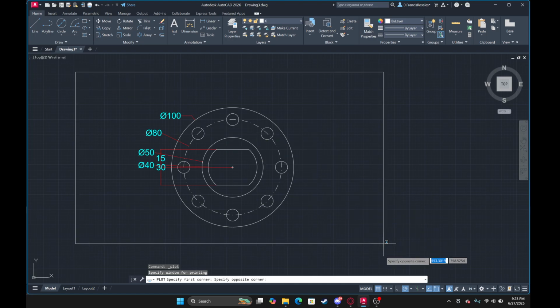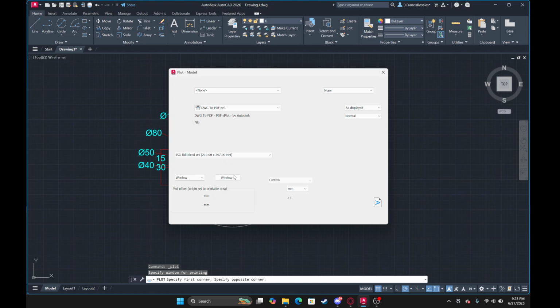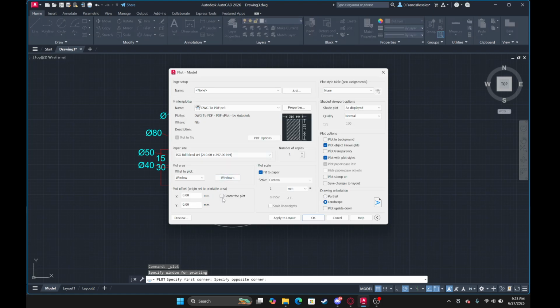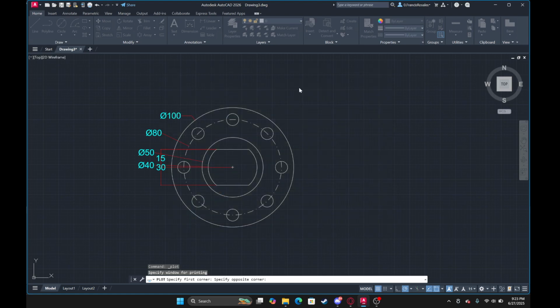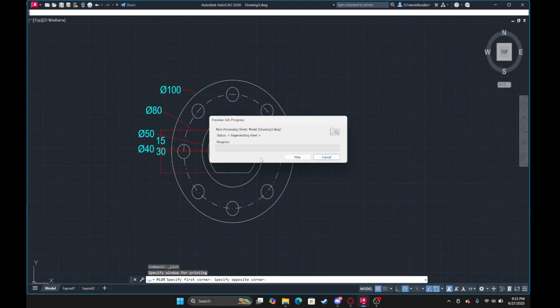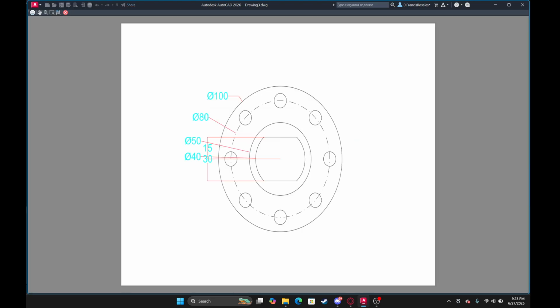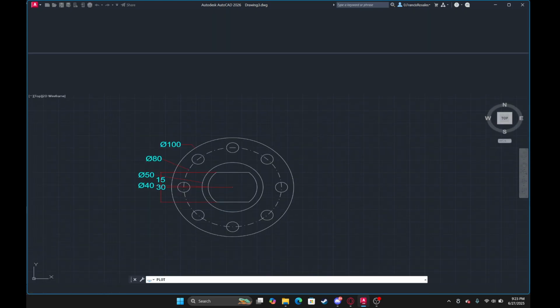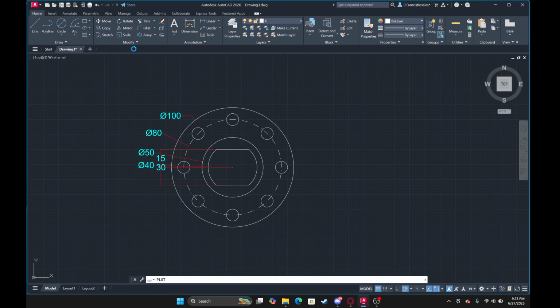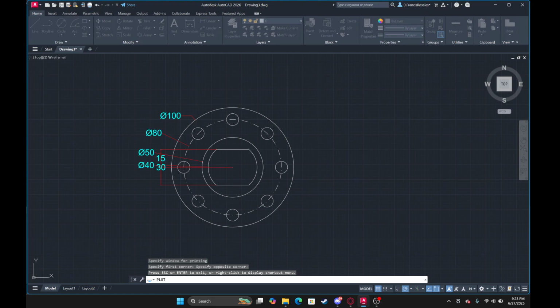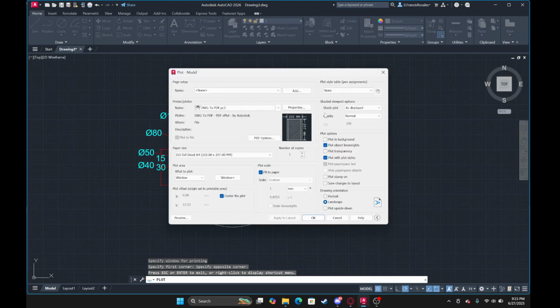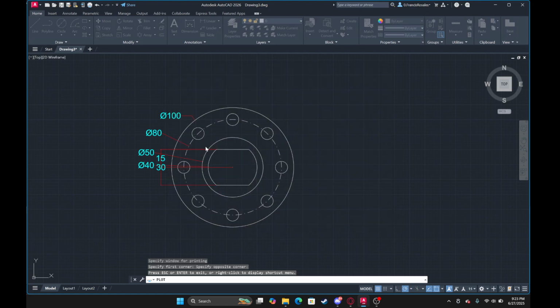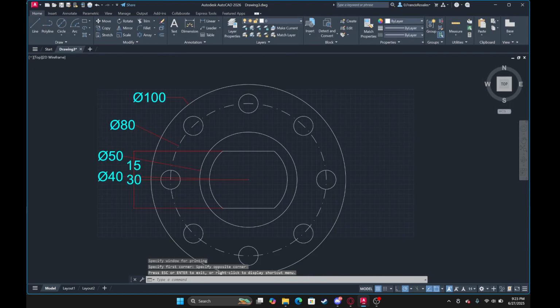Then display type window. Let's select this over here. Let's center it to the plot and apply layout. And we can preview what it looks like on paper once you print it. That's what it looks like on the paper. You can also make your own template using rectangles, lines, and text, and you can select the whole template. I'm not gonna print it. It's just an example project. So yeah, there you go.